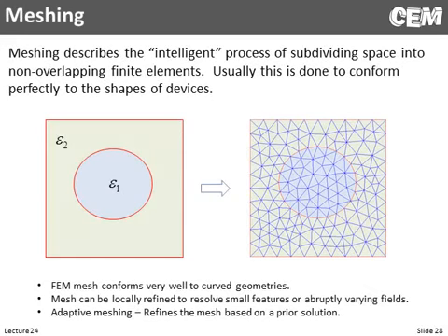So finite element always starts off with meshing. Before we even get to the math of solving the differential equation, we have to describe our geometry with a mesh. And this is a rather advanced thing. There's been many PhD dissertations awarded just on meshing algorithms. So I would put this actually at higher importance than the actual Galerkin finite element itself.